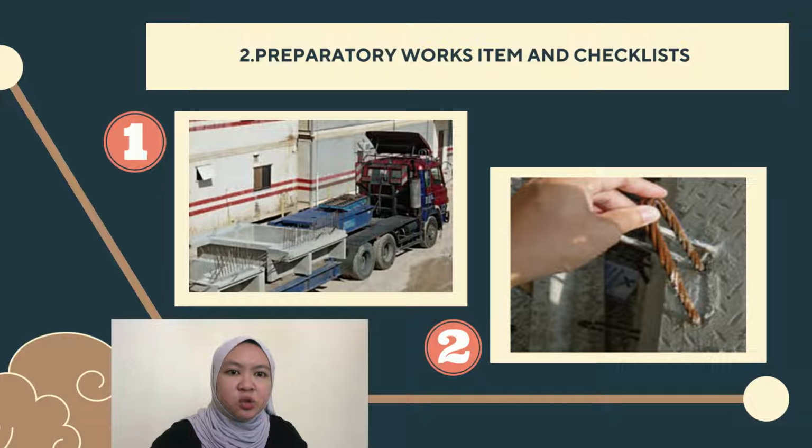The first step should be to ensure that the site is accessible for the delivery of precast elements. Check the delivery checklist to ensure that the right kind, quality and panel identification are used. Check the crane capacity and operation for the proper hoisting of precast concrete components, as shown in figure 1. Then a visual inspection of concrete finishes should be performed to look for any defects. The most important thing to perform before hoisting is to double check the condition of the lifting insert to ensure that the components are safe during the lifting work, as shown in figure 2.